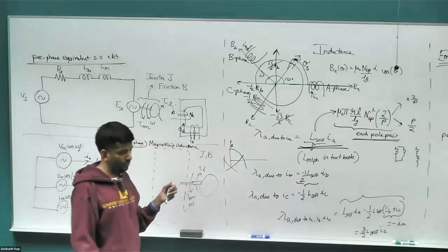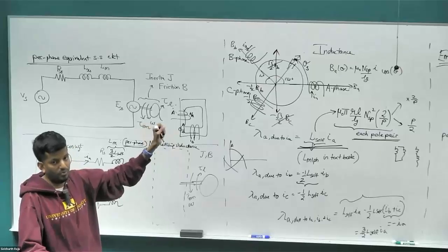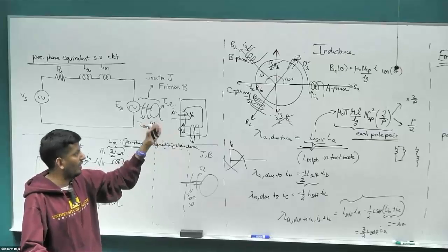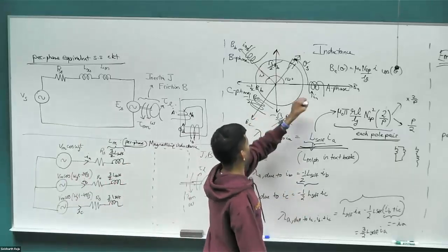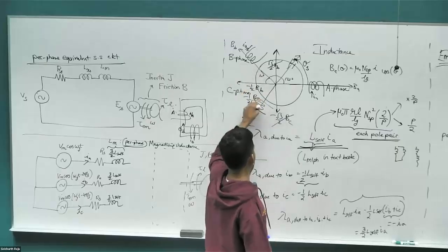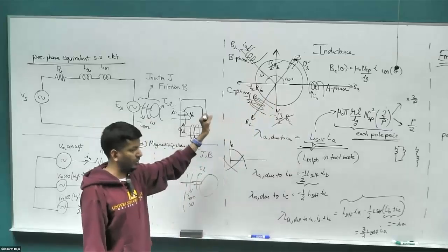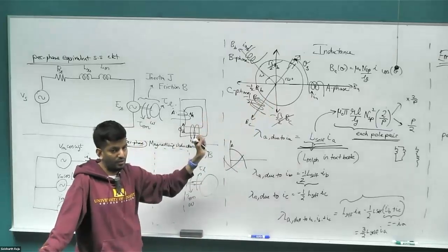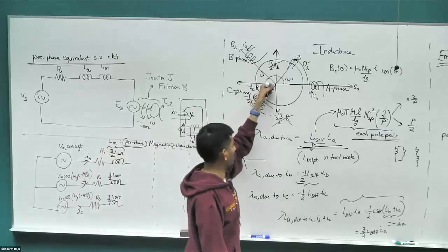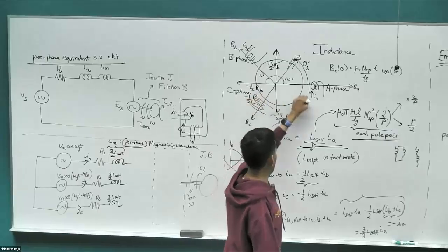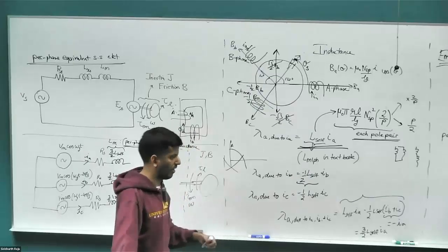So this is a very useful tool. This happens to be so because of the way our winding was wound in a sinusoidally wound motor, sinusoidally distributed winding. You get this nice way where you don't have to go through the process of deriving the equation all over again. Just diagrammatically, you can visualize these inductor coils and exactly figure out what the contribution of this flux would be to this flux. It's just a pure property of sinusoidal distribution of winding. If you had some other kind of distributed windings, it won't happen that way. Many textbooks use this as a way to derive it, but that's not the way to derive it. It's just a happy coincidence that it comes out in this nice way. But for different distributed windings, it will be a completely different profile.